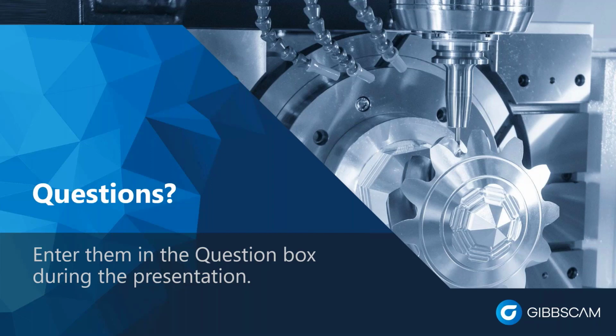Absolutely, yeah. On a 3-axis mill, as we were displaying there, you can easily use the 5-axis module, lock out the rotary axes, and have yourself a 3-axis toolpath creation engine. It creates very strong 3D toolpath operations. There are also, which I didn't show here, some very effective roughing strategies within the 5-axis. As I was saying, that adaptive roughing is available in different sections of the 5-axis module.